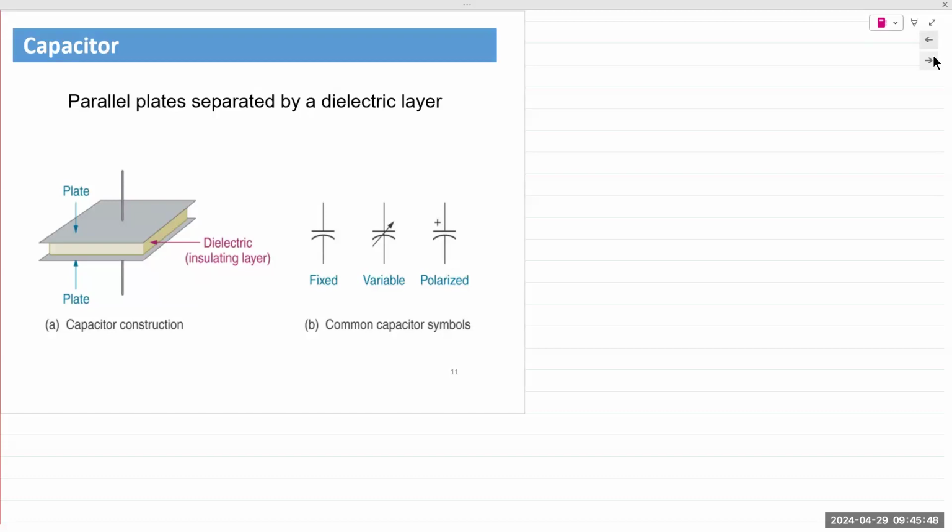Sometimes if it's just a charging cable, it might just have 2. But all of those conducting wires have to be separated by an insulating material, right? So you have 2 pairs of conductors separated by insulating material. Across the entire length of that cable, there's a capacitance that you can measure. But again, that capacitance does not rise to the level of interference with that functionality.